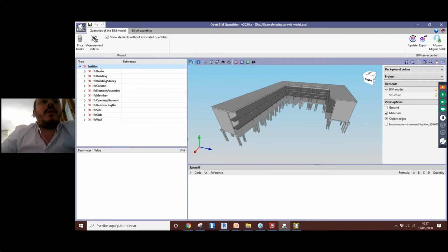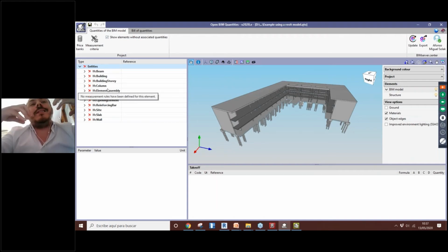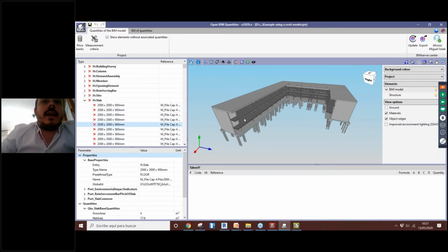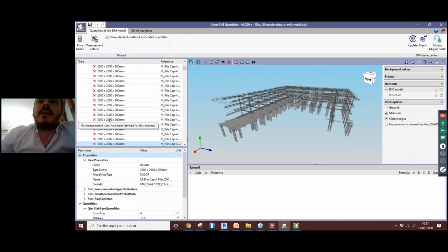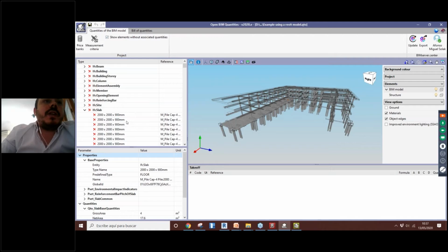So inside of this BIM model, we have some IFC entities. They are all with this red signal here. It means that this information is not connected yet. So we didn't define this association between these elements yet. For example, if we open here, we can see that, let's put this in a transparent view. It's going to be better to see. So for example, this list of elements are exactly the elements that we have in our model.